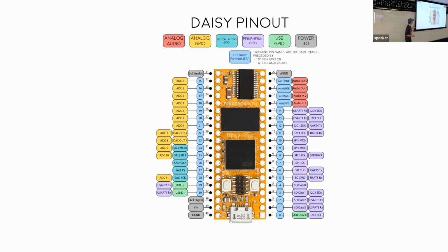And so we need to find out which UART RX receive pin. By the way, TX is transmit, RX is receive. We could use any of these. There's UARTs here, and you can connect to UART3, UART4. It turns out we don't need to make the decision because libDAISY has it hard coded to these pins. But if you wanted to edit libDAISY, you could set it to any of these. But a question arises: